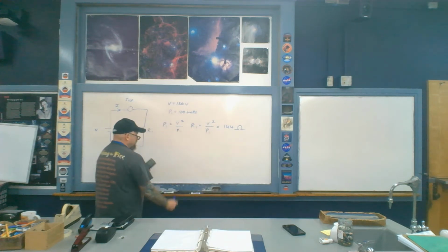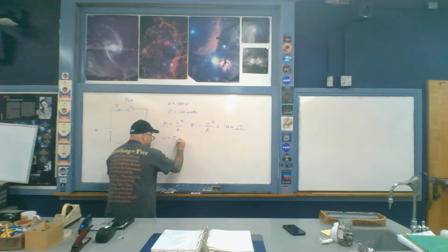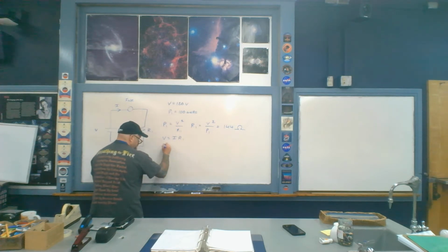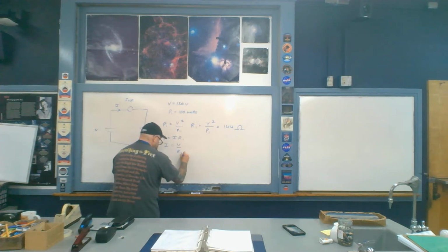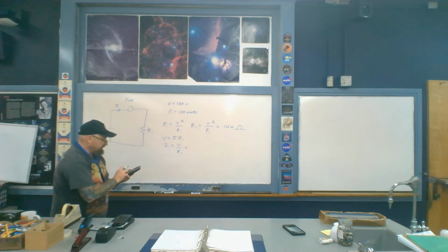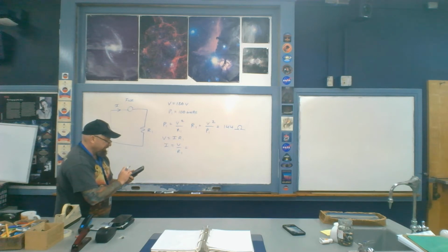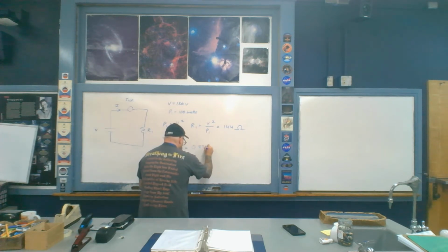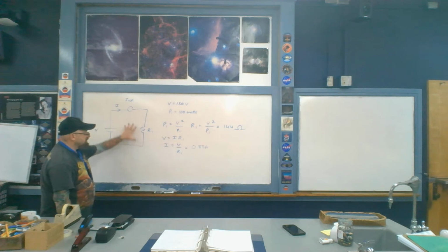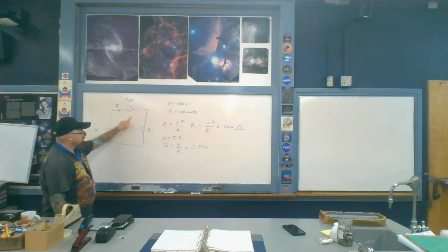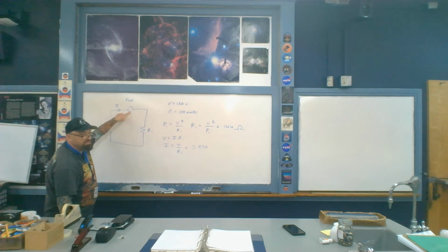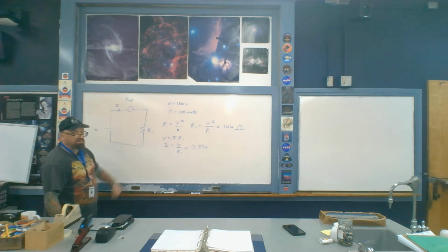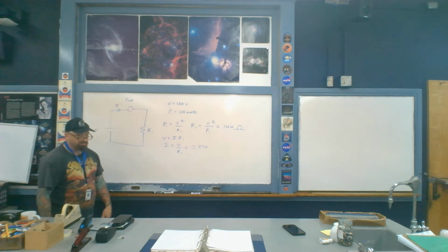And this comes out to be 144 ohms. Okay, and now that voltage is equal to I times R1, so let's go ahead and calculate the current I. So V over R1. So then therefore that's going to be equal to 120 divided by 144. Okay, and that comes out to only be 0.83 amps. So that's the total amount of current that is flowing through the circuit right now. That's not going to melt this fuse or trip the switch here. In other words, we could safely operate this light bulb.